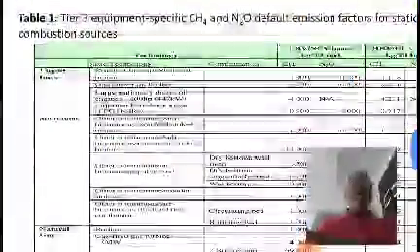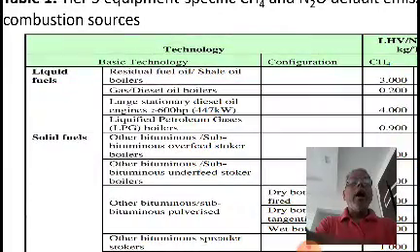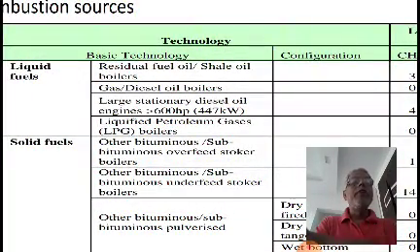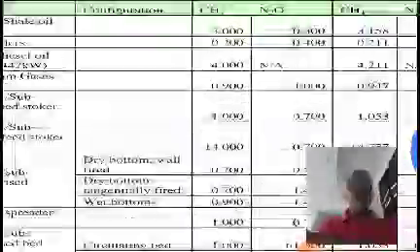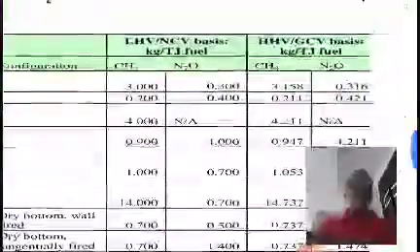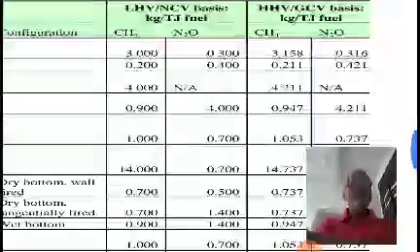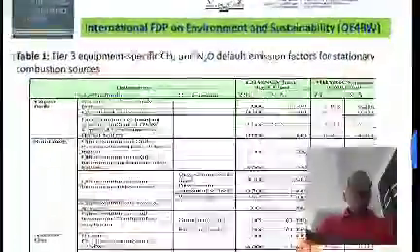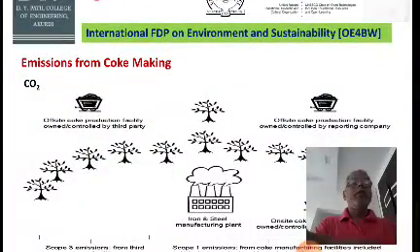You can see here in this table 1, all these factors are given according to the fuels, whether it is liquid fuel, then residual fuel or gas fuel, then solid fuel, natural gas, and accordingly the LHV or NCV, net calorific value. These values you are getting, and this is the standard value, right? So from this you can select the value, substitute it in that equation, and you will get the CO2.